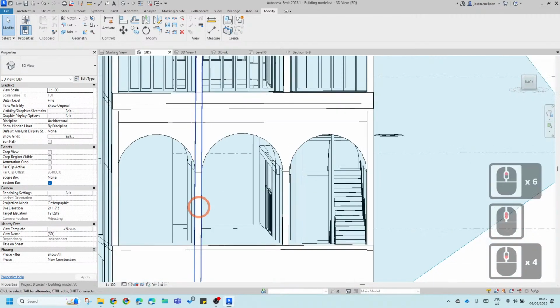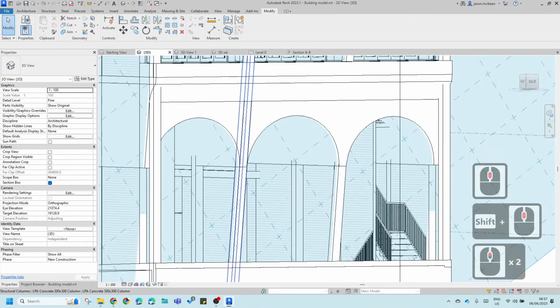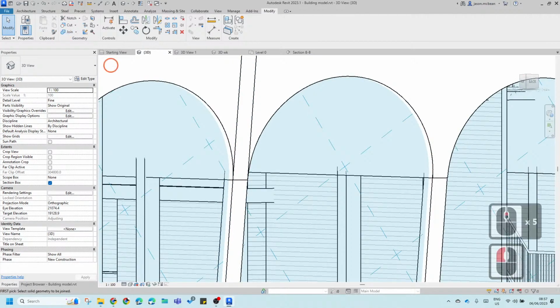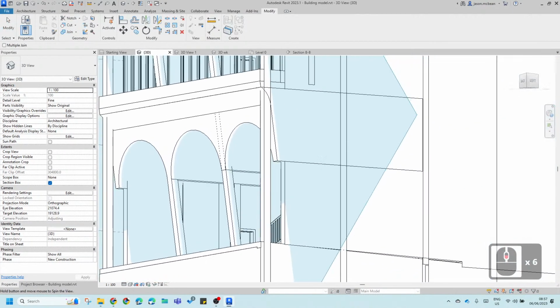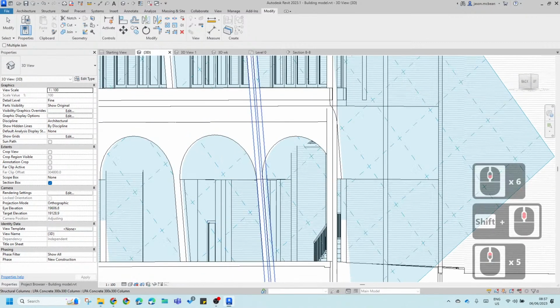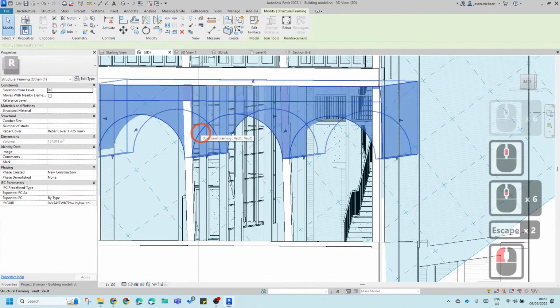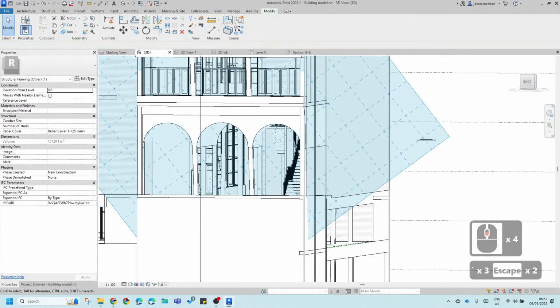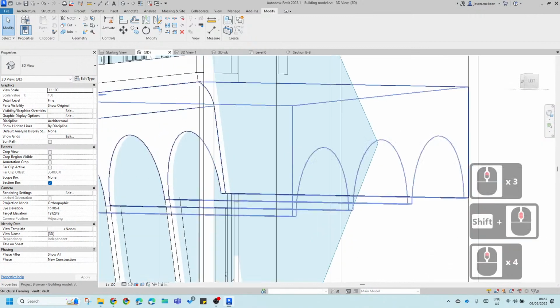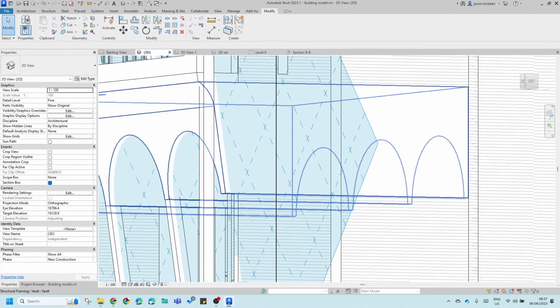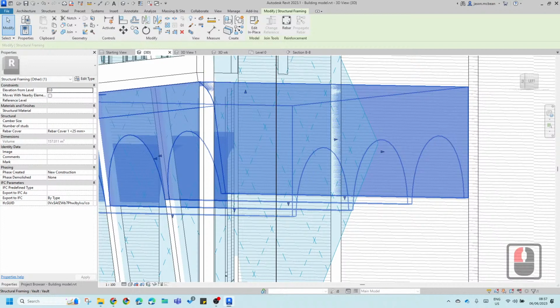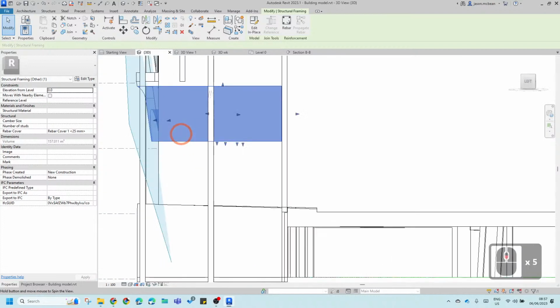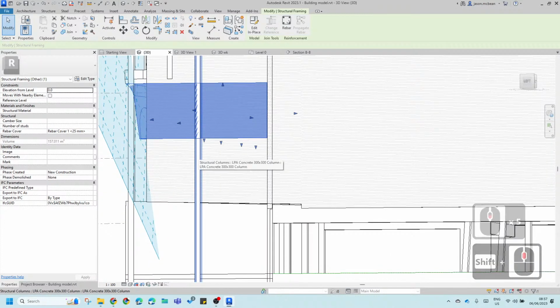If you make it structural framing, then what you can do is join. Now, provided they've got the same material as a column, if you say join, oh, and it's seamless. But provided this is a structural framing or column, because then it's behaving like structure. That's cool because you maybe want to join this to the slab. But then you can also punch out voids. So now you can cut a big arc in there, or you can make it flat.